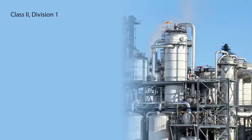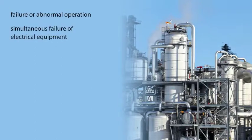Class 2 Division 1. Locations where combustible dusts are suspended in the air in quantities that produce explosive or ignitable mixtures under normal operating conditions. Where explosive or ignitable dust mixtures are produced because of failure or abnormal operation of process machinery or equipment. Where such failure of machinery or equipment would also provide a source of ignition through the simultaneous failure of electrical equipment. This class also includes areas where electrically conductive combustible dusts may be present.